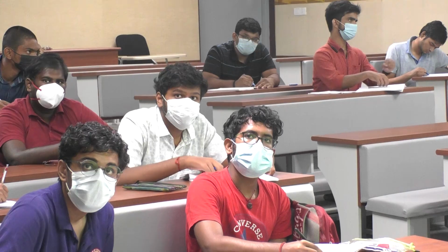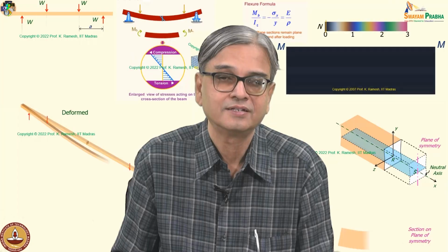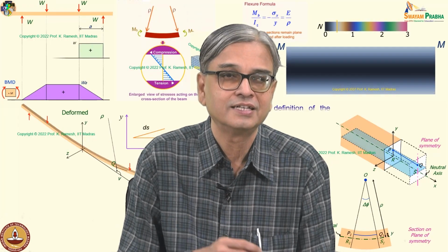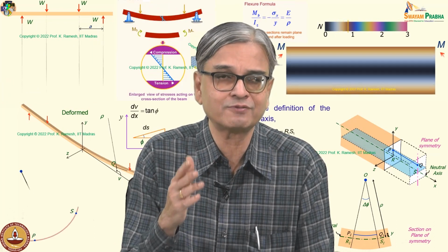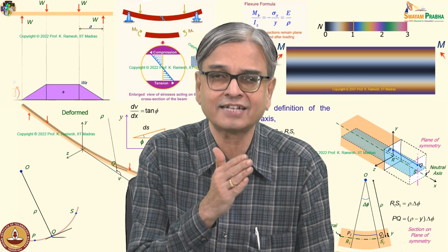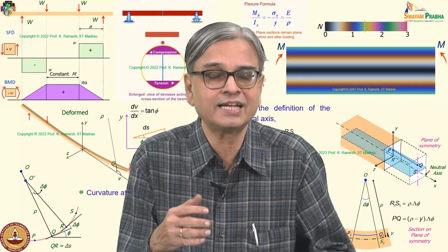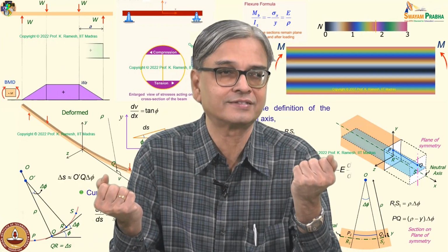And can you write anything about epsilon y? Does that exist or not? See, you have studied strength of materials so far. When I apply bending moment, we have seen that axial strain varies linearly. So, you can imagine that the loading has caused some kind of strain in one direction.